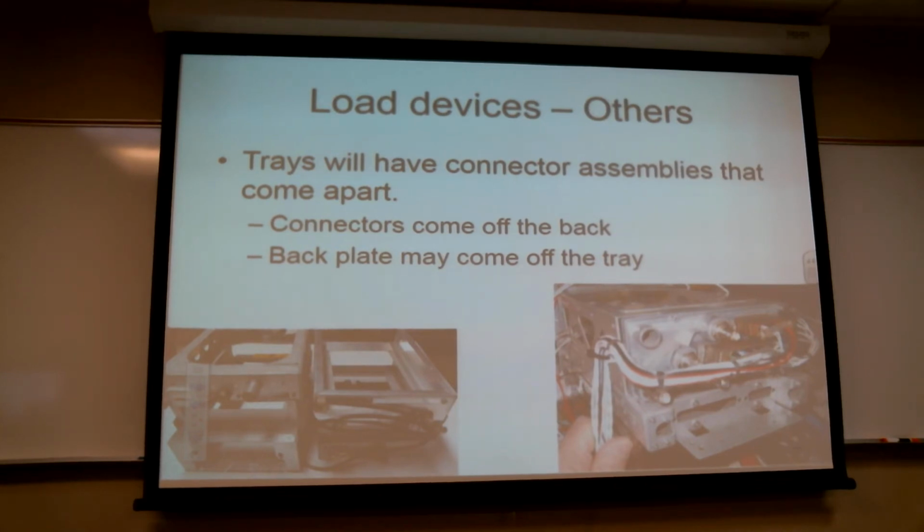So let's see, on the 430, you're going to have the glide slope, the ILS, and the comm radio, I presume. And then somewhere, actually no, one of these serial lines will be your line in from the GPS antenna.